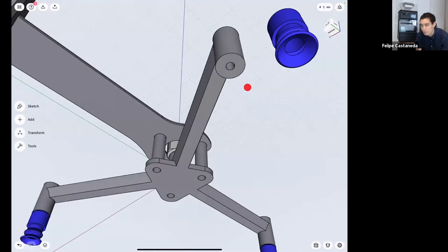Yeah, and I remember the first couple of times, back in the day when I started modeling in 3D, how easy it was to generate pseudo solids that were not completely closed. So if you wanted to print them out, they would have holes in them, or they would simply not print. The slicer would just break because you're trying to export a series of surfaces that on the render might look like a solid, but it's just basically patches here and there instead of a completely solid body. Absolutely.